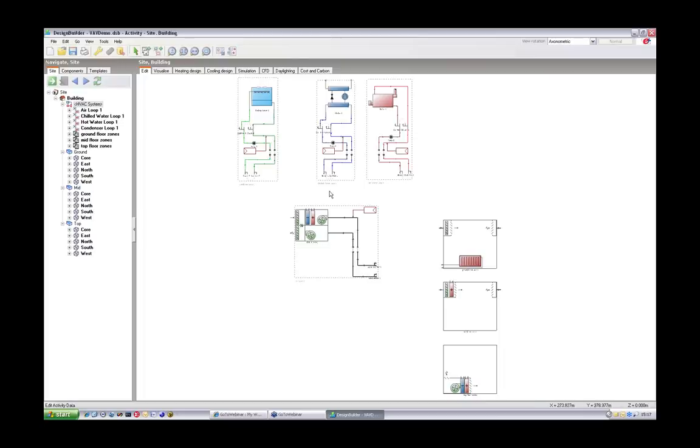Okay, EnergyPlus includes a feature which allows you to define various plant operational schemes. The idea being that you can model scheduled sequencing of plant equipment depending on time-varying load requirements. For example, you may want to model a modular boiler system and schedule low-load modules to handle loads up to a certain magnitude, and then switch in more modules as the heating load increases.